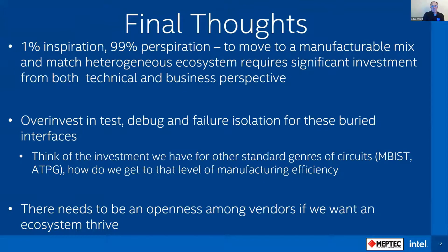So to move to a mix-and-match heterogeneous ecosystem, I don't think anybody disagrees with it. It requires a significant investment from both a technical and business perspective. And given that this is silicon, it's not like you can make a mistake and fix it. Kind of the FPGA fallacy. Once it doesn't work, you have to respin those masks. Again, this has been my rallying cry for 30 years: overinvest in test, debug, and failure isolation for these buried interfaces.